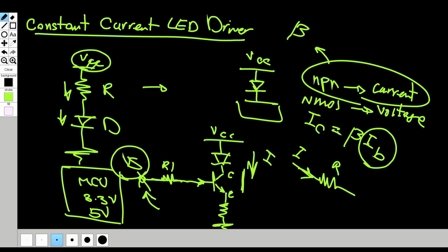It's a little bit hard. There are devices that can sense current directly, because they're current sense devices. But most of the ICs that you see out there actually sense the voltage across this resistor in order to find the current through it. It's just simple Ohm's law.